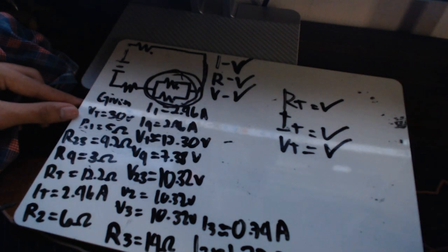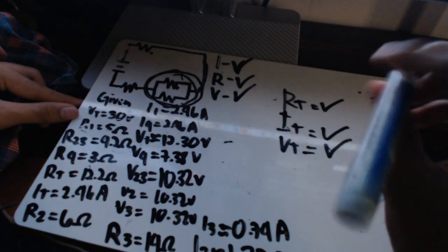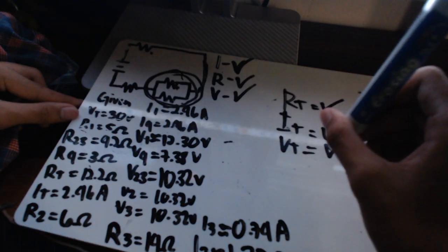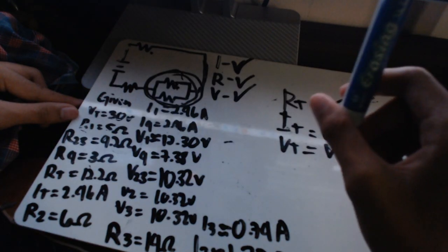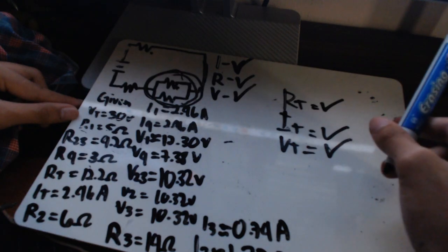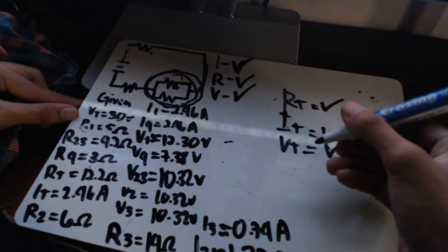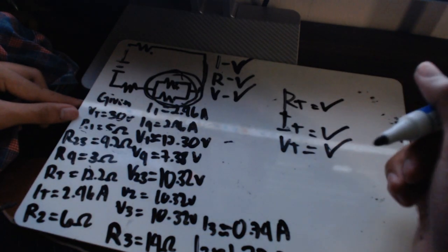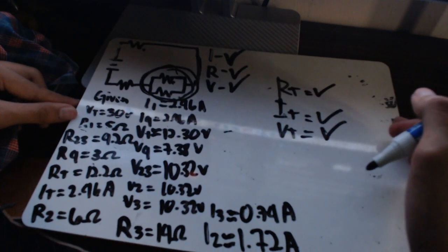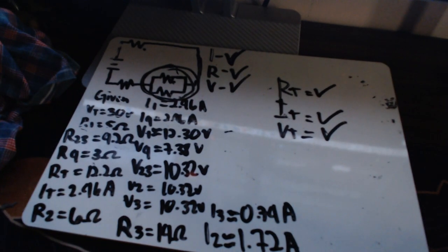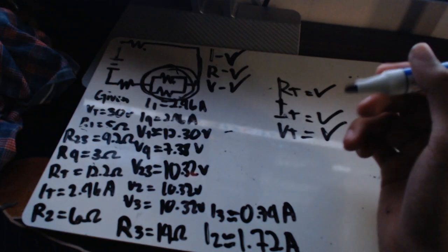So the main thing to remember is identify the series and parallel sections first, and simplify the easiest section first, and then work backward through the circuit. Once you practice this process, even a complex circuit becomes much easier to solve. So this is the full solving flow.